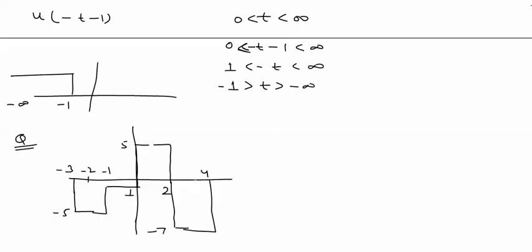We can write down the expression for this given diagram. How can we write it? We start from the minus 3 time reference, and the amplitude is minus 5. So first we put minus 5 amplitude, starting at t location minus 3: minus 5 u of t plus 3.